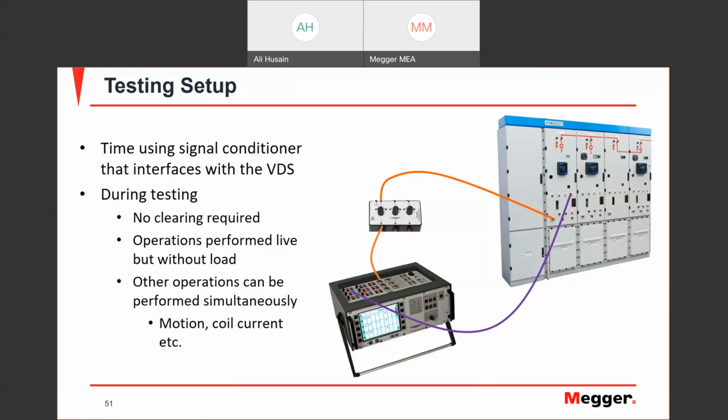But there are some things to look for. The breaker must be live. There has to be a voltage presence, but it should not have any load current in it when you want to perform this test, since any load currents could introduce some arcing or something like that that will give you measurement errors during the test.